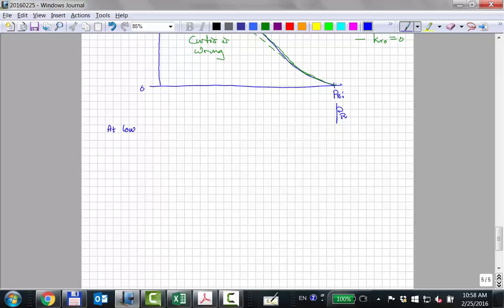At low pressures, Ki, and now we're looking at C5 and heavier components, is basically equal to 1 over pressure. So if you get to low enough pressure, those K values are increasing significantly, to the point where those components want to start moving to the gas, because the higher the K value, the more that component wants to be in the gas. So it's because of that.